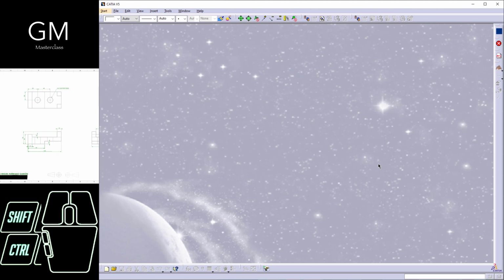And the second thing that we are going to do is to select one of the views for us to start creating our model. How are we going to do that? By selecting the view that contains the most information possible. Right here I have 1, 2, 3, 4, 5, 6, 7, 8 dimensions. Right here I have just 2. Right here I have 1, 2, 3, and 4 dimensions. So I'm gonna start creating this sketch by using this view.